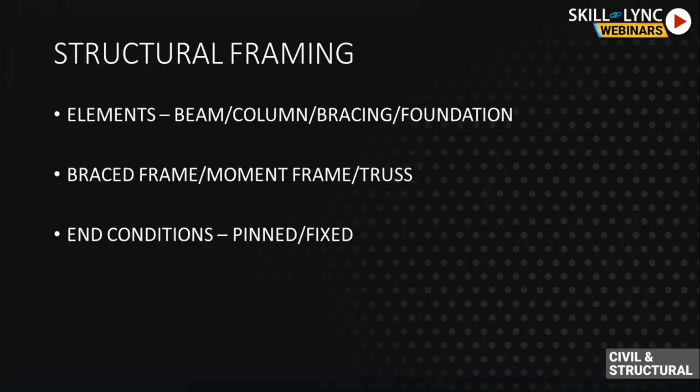End condition. If it is a steel structure supported on a concrete foundation, there has to be an interface between the steel and the concrete. That is what we call the end condition, pinned or fixed. If it is a purely concrete building, in that case also there is an end condition.